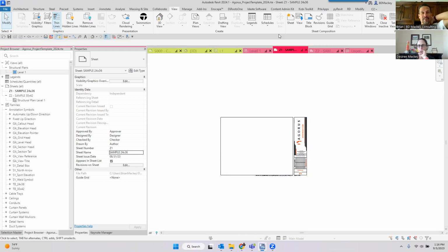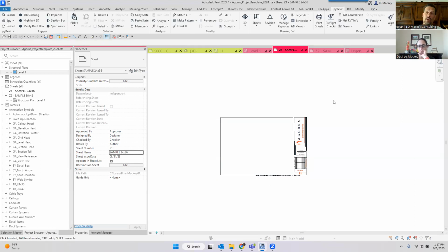So yes, this was a lifesaver for me, the pyRevit tool. Because prior to that, what did you do? You linked an AutoCAD file from 0, 0, so you have a little line from 0, 0. Then you draw a reference plane, then you'd unlink that AutoCAD file. It's kind of a pain in the butt. Added in about putting in reference planes at the corners.